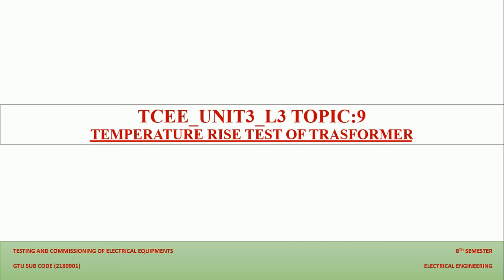According to the given permissible limit, the temperature of the transformer may increase, and if it increases beyond the limit, it will harm the inner parts of the transformer. So we need to perform the temperature rise test to check the performance of the internal parts, and from that we can improve the life of the transformer. So let us discuss this transformer temperature rise test in detail.